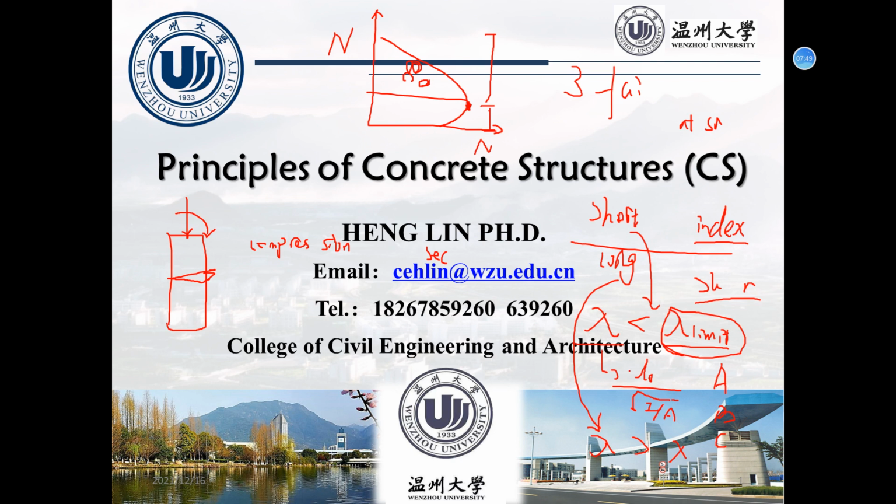Now, talk about the effective height L0. It is related to the boundary conditions of the column. If it is hinged and roller, the effective height equals exactly the height. If one side is fixed and the other side is free, the effective height equals 2 times L, where L is the original height of the column.